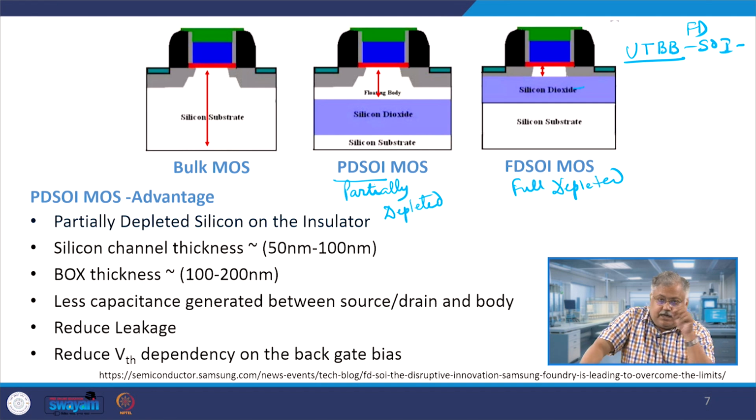So effectively it insulates the source and the drain, and that is the reason it does not form parasitic capacitances. Similarly, the insulating layer also confines the flow of electrons from source to drain in one direction only, and therefore reduces performance, degrading leakage current factors.